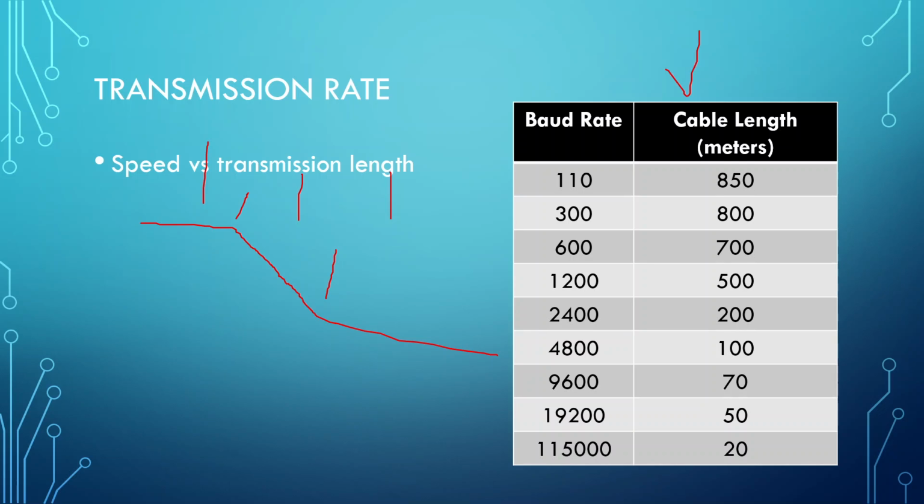This table right here is based on field tests, so this isn't theoretical math saying according to the math we can do this. We've actually tried this, and in the test environment where this was done, these were the baud rates that worked. Now the other nice thing here is 9600. That is probably your most standard baud rate, the one you will probably see most often, the default go-to.